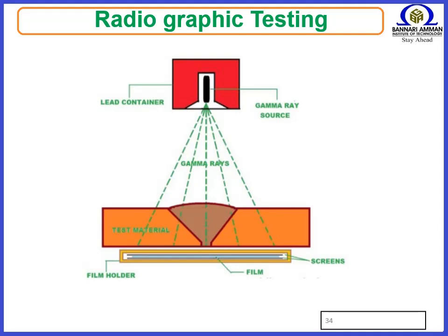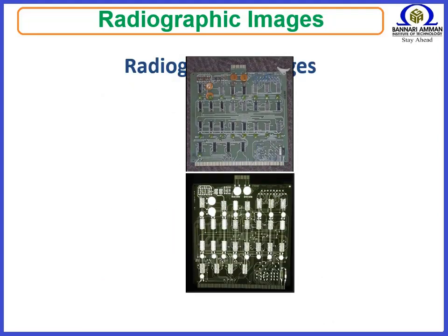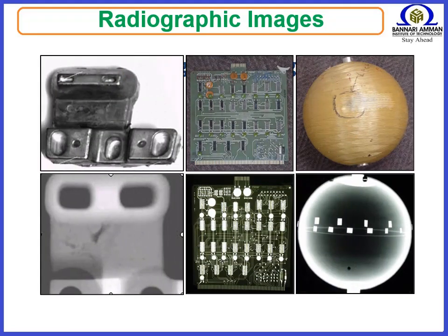These images are available for viewing and analysis in seconds compared to the time needed to scan in computed radiography images. The increased processing speed is a result of the unique construction of the pixels, an arrangement that also allows a superior resolution than is found in computed radiography and most film applications. Radiographic images are shown in figure.